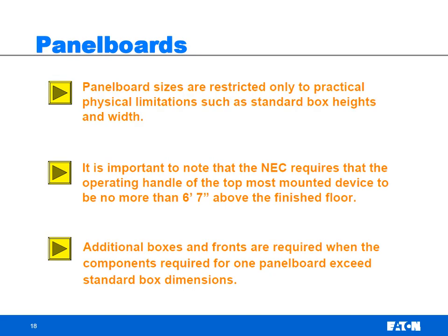Okay. As far as sizing, panel board sizes are restricted only by practical physical limitations, standard box heights, standard widths. This is probably the number one driver as far as box height, that it is important to note that the NEC requires the operating handle of the topmost mounted device to be no more than 6 foot 7 inches above the finished floor.